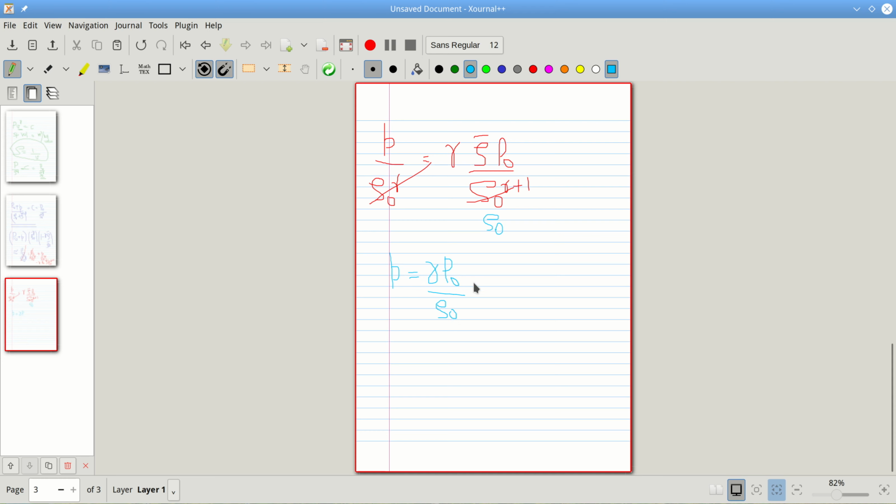So this is the relation that we have. The acoustic pressure fluctuation amplitude small p is related to the acoustic density fluctuations rho bar by this constant, which involves the mean atmospheric pressure and density, and this gamma is of course the adiabatic coefficient associated with air, which is 1.4.